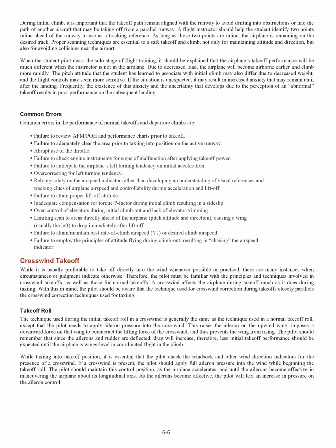Common errors in the performance of normal takeoffs and departure climbs are: failure to review AFM/POH and performance charts prior to takeoff, failure to adequately clear the area prior to taxiing into position on the active runway, abrupt use of the throttle, failure to check engine instruments for signs of malfunction after applying takeoff power, failure to anticipate the airplane's left-turning tendency on initial acceleration, overcorrecting for left-turning tendency, relying solely on the airspeed indicator rather than developing an understanding of visual references and tracking clues of airplane airspeed and controllability during acceleration and liftoff, failure to attain proper liftoff attitude, inadequate compensation for torque/P factor during initial climb resulting in a sideslip,